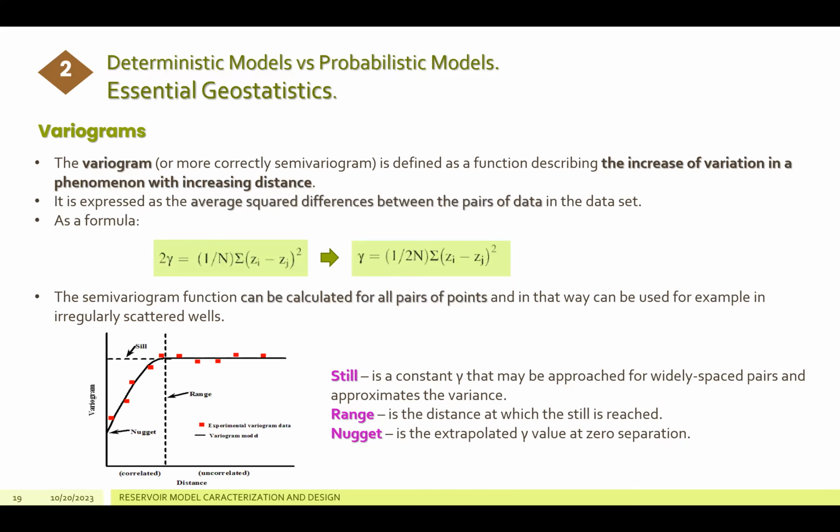You can ask an external person, and maybe that person sees that you did an approach to your variogram that is not proper. "Let's try to give more importance to this part over here, reduce this part over there." So you can adjust your variogram and you can see this adjustment in your model. This is one of the things, okay?